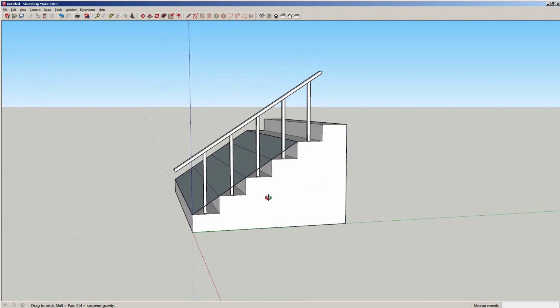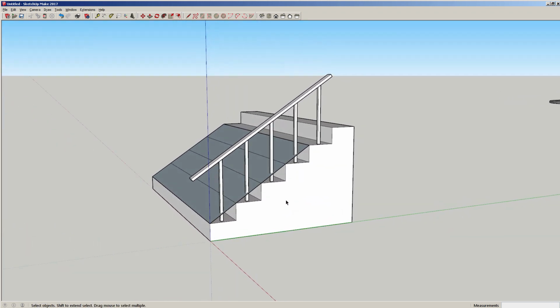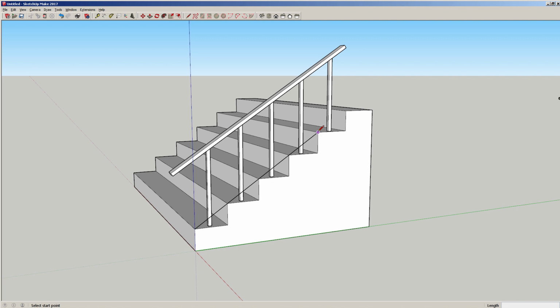So there's kind of a bank, right? It's a steep bank. It's still a bank. In fact, I prefer doing it the other way. Let's go down, hold shift to snap to the blue axis, and roll your mouse over the very end of that first line. There we go. There's our bank. It's not reaching the ground yet. We can fix that later.